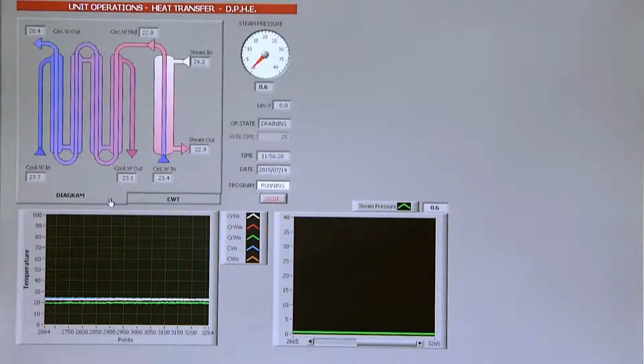So when you push the button, you provide a 5-volt signal to the computer that tells it to start filling, and now I'm filling. Once the switch is pushed by the water, it turns it off, and then that 5-volt signal goes to 0 volts again, and the computer shows you the time elapsed. Because the volume is fixed, you can divide that volume by the time, and you get the flow rate of the steam that we have been using.